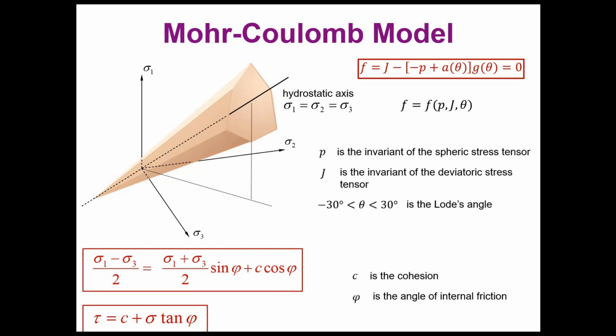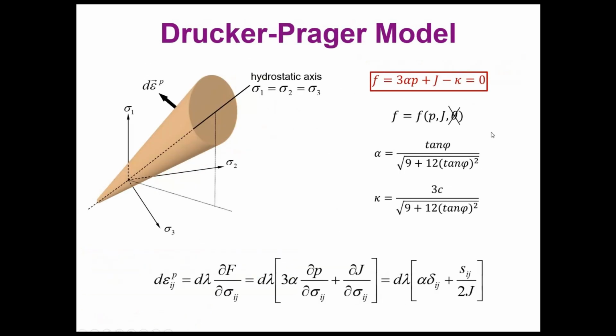The strength of the soil depends on many factors, but it's not only a property of the soil; in this model, the strength of the soil depends as well on the level of effective stresses. So this is the reason why the shape of this model is different. It's a kind of pyramid with an irregular hexagon as a base. And again, this can be capped at some stage, depending on your needs to reproduce reality. But this is one of the reasons why this is popular.